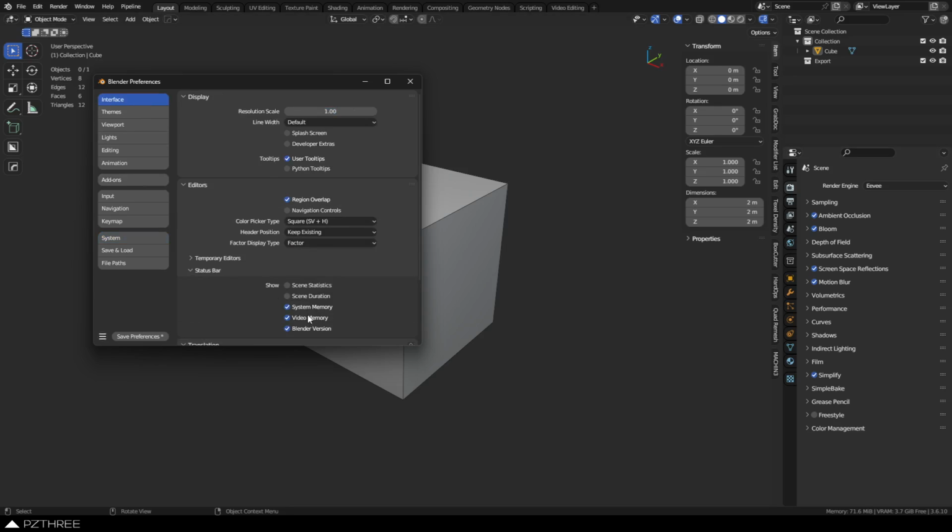Now this lets you more or less see how much resources your system's using in order to generate what's in the 3D viewport here. You need to monitor this as you're creating things and think about what you're using, when and where. It's about how you use your assets, but also you don't need 8K textures for everything in your scene. It's not always going to improve the quality or the results of the render, right? It's about cleverly placing things and using your assets as repetitiously as possible without creating, well, repetition in the render. So anything that can be repeated and doesn't seem like it's repeated too often is worthwhile.